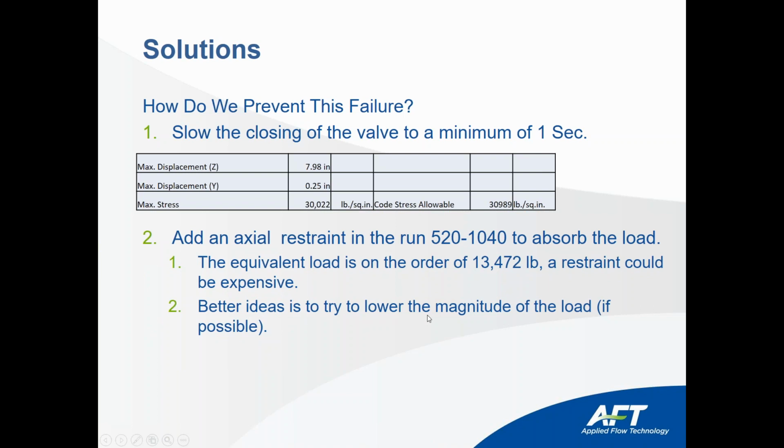So a better idea is to try to lower the magnitude of the loads as much as possible, like we did using a valve, or you can use a surge tank, which is another solution you can think of.